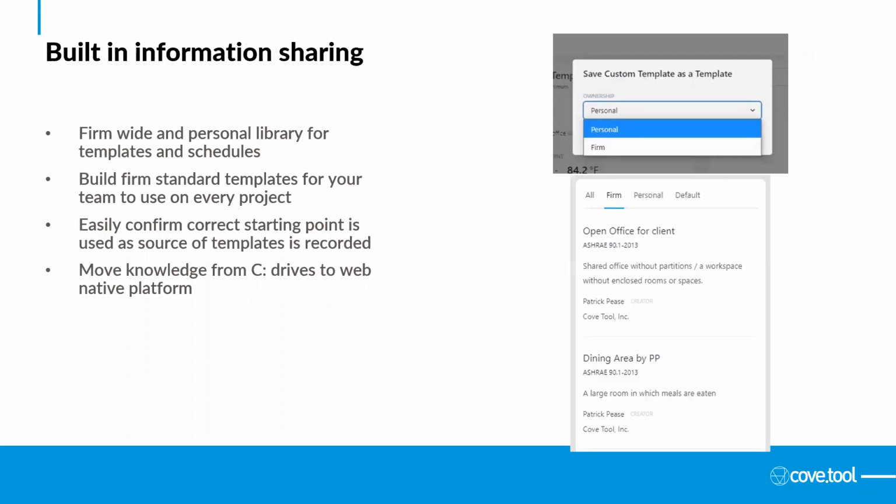Another thing we've integrated straight into the tool is built-in information sharing and, we'll call it, storage and growth. So right off the bat, we have a function to save templates and schedules into either a personal or firm-wide library. And what this allows firms to do is create the library or catalog of the templates that they use every time they do a load model. So say they have a specific client and their offices always have a specific schedule, a specific plug load. Maybe they do denser people than the standard ASHRAE value, that can be saved and assigned.